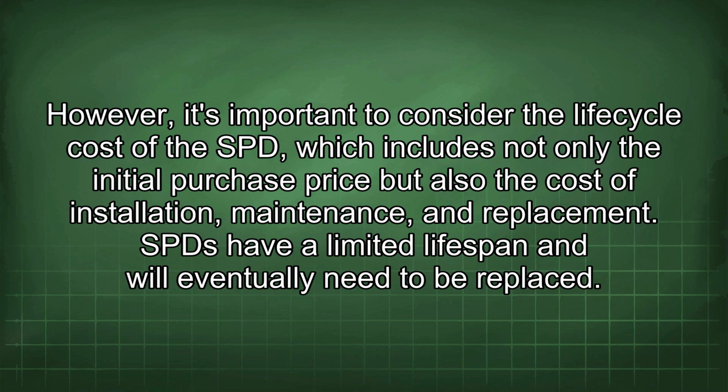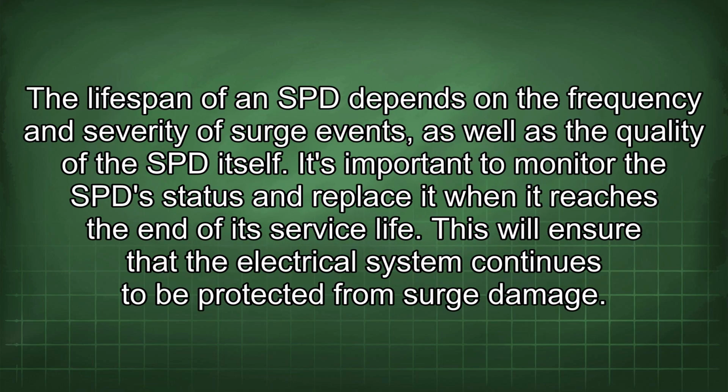SPD have a limited lifespan and will eventually need to be replaced. The lifespan of an SPD depends on the frequency and severity of surge events, as well as the quality of the SPD itself. It's important to monitor the SPD status and replace it when it reaches the end of its service life. This will ensure that the electrical system continues to be protected from surge damage.